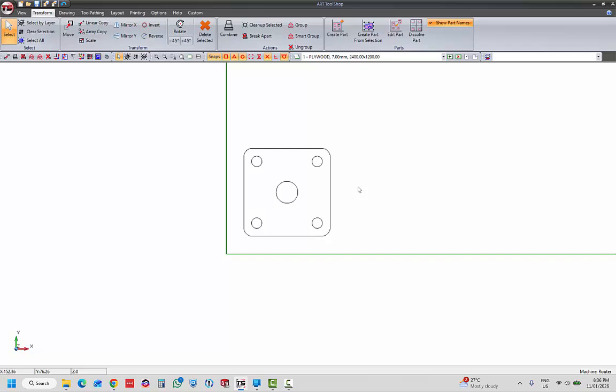To sort the shapes into parent and children shapes, we simply select all the shapes belonging to the flange. Then we go to the Transform menu and choose Combine. This can also be activated with the Ctrl-L key combination. You may remember this as L for linking the shapes.